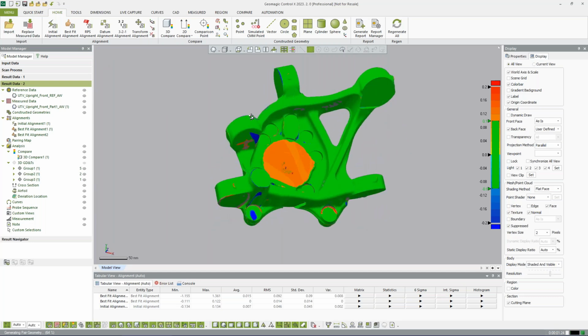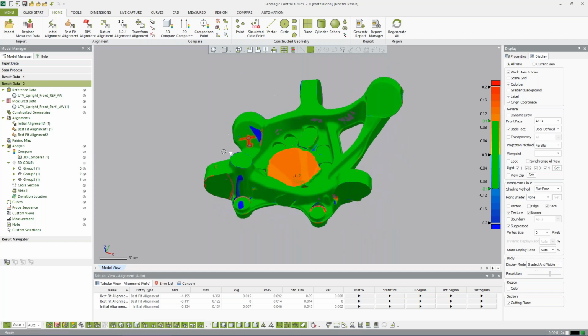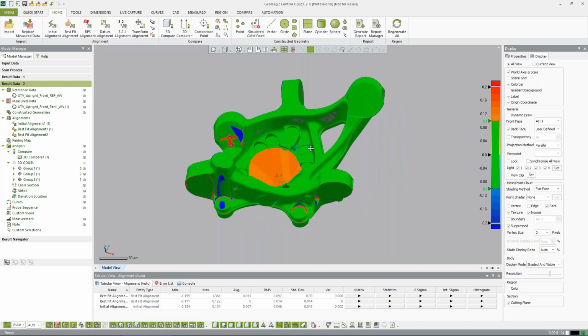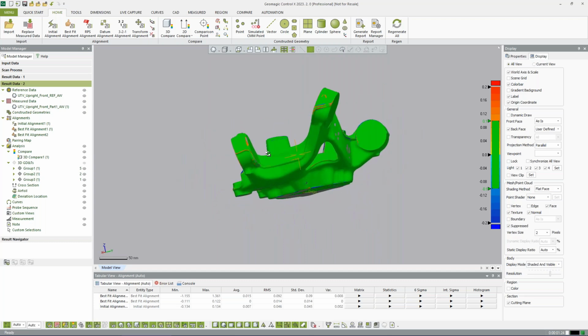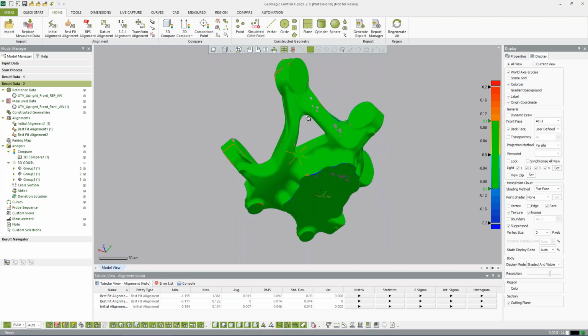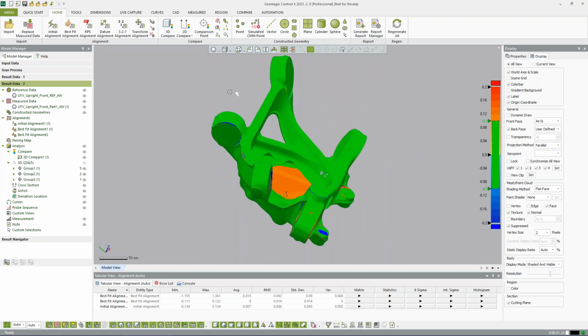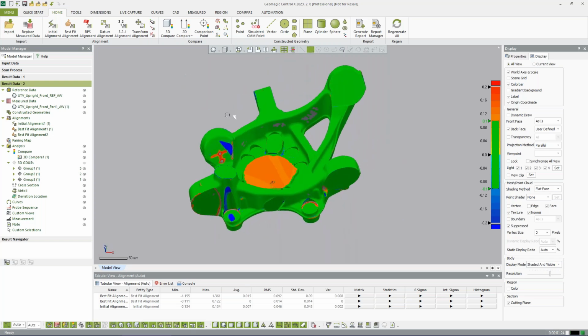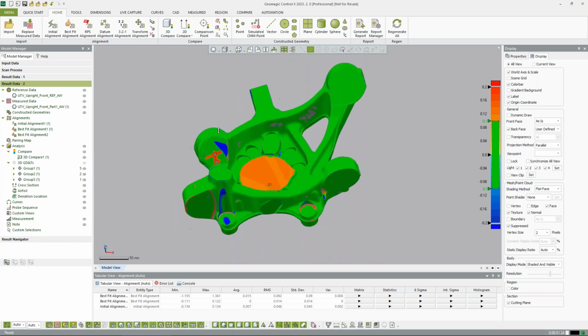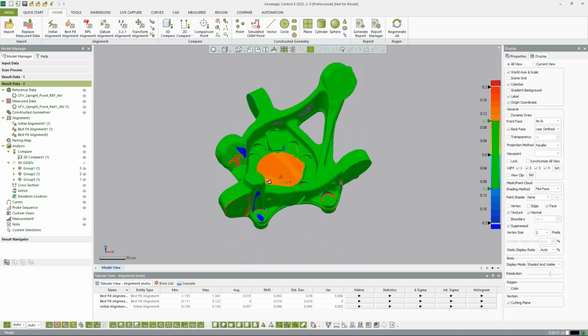So if I push the alignment like that to some other features, even ones that I know were under machined based on dimensions, and I float them all in and they all fit, and then nothing else changes on the part, I know that I didn't shift anything in one particular direction or the other. So there are a lot of investigative tools in here for scan-to-scan work in your processes.